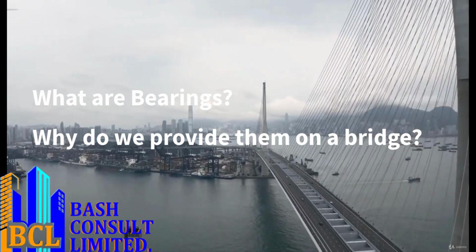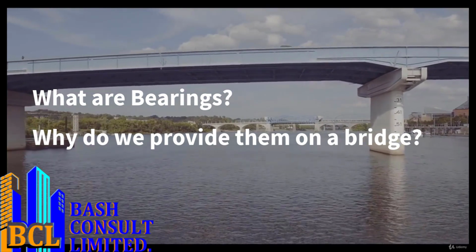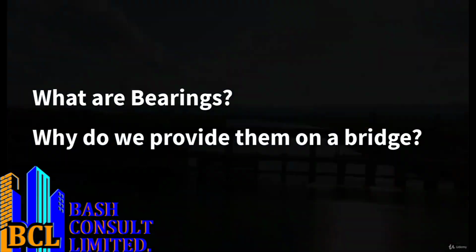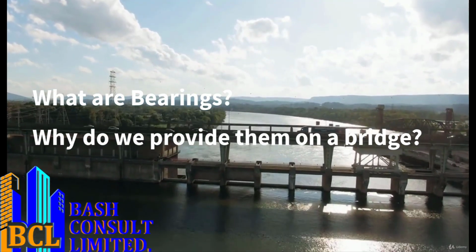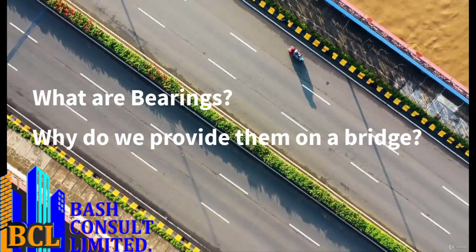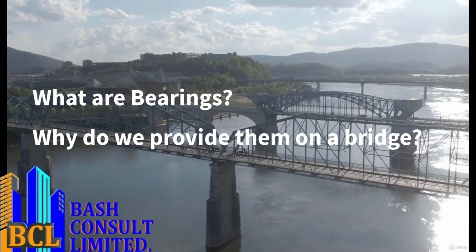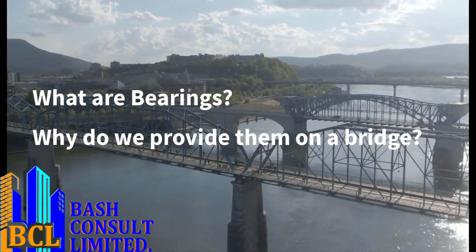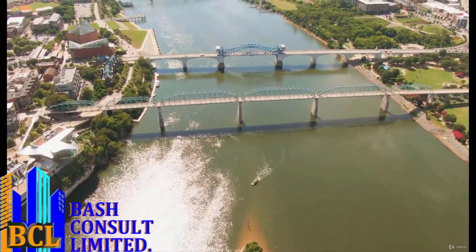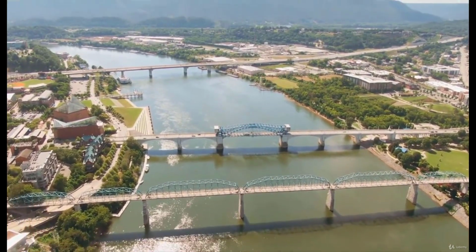They help in transmitting live load from the superstructure, dead load, wind load, earthquake, and impact loads. Their main function is to transmit the vertical load from the superstructure to the substructure. They also facilitate movement of the superstructure due to thermal expansion and contraction. There are various forces that act on bearings which necessitate their importance on a bridge. We have the longitudinal forces, the transverse forces, the reactive forces, and some uplifting forces due to earthquakes.